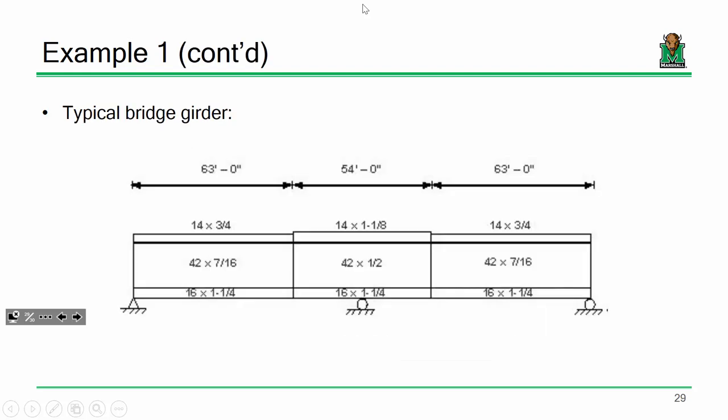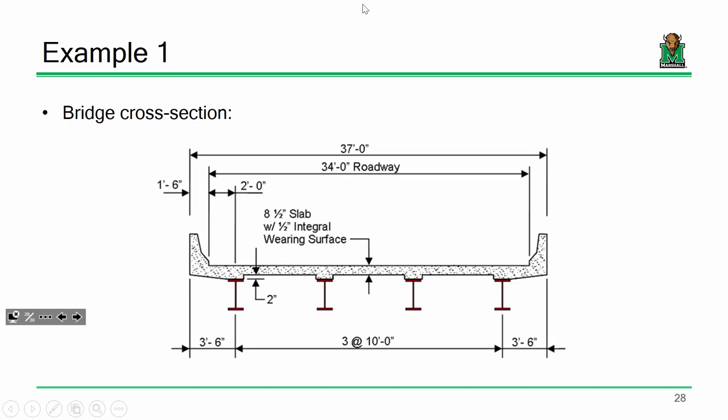All right, so we looked at this structure, and we went through and discussed how to compute non-composite section properties and then composite ones. And what we found was it really doesn't matter. Once you've gotten the composite section properties down pat, they're all the same, really. What's the difference between short term and long term? It's just a different N value. Instead of N, it's 3N.